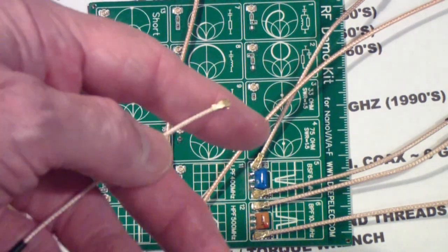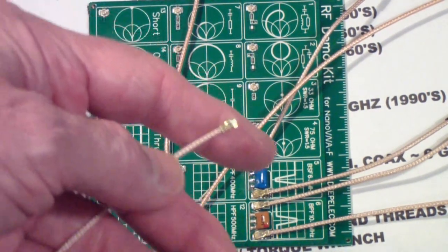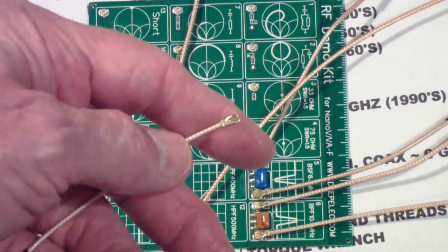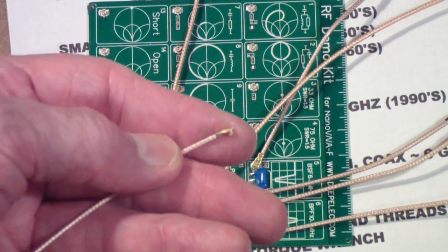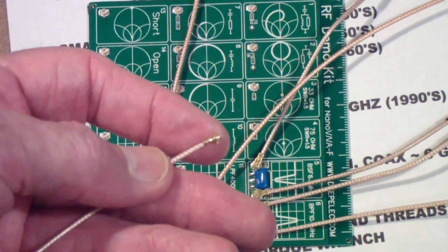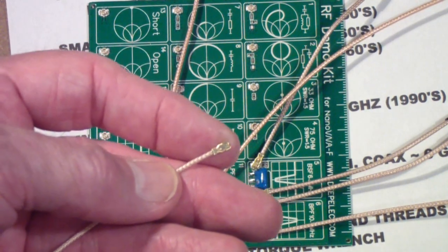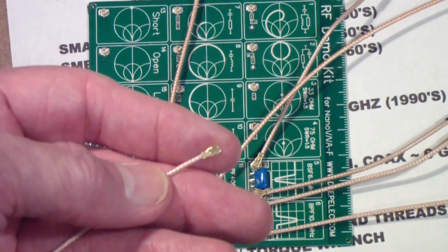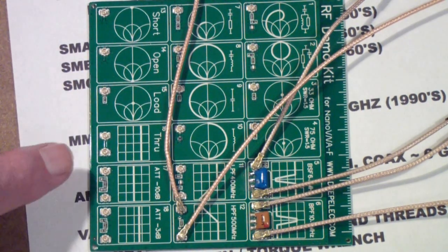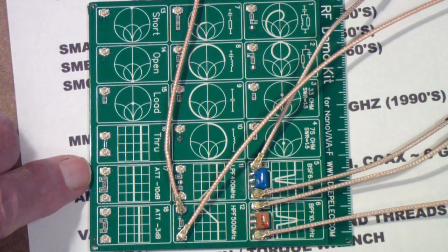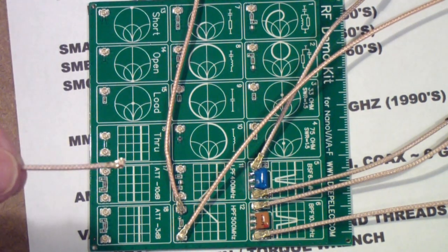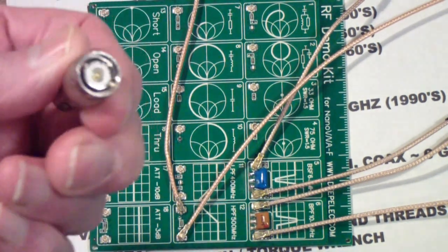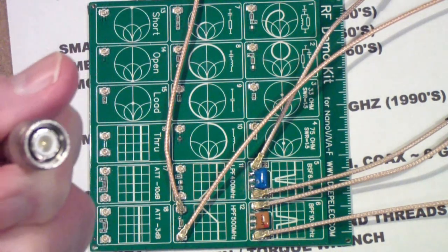So the UFL and later the AMMC by Amphenol are connectors intended to be very low profile, but they are coaxial connectors. I'm sure you can't see that, but there actually is a coax inside, a pin inside that connector, and it mates to sockets like this. Now, one thing that I will point out with these kinds of connectors, they are not intended to be mated and remated like something like a TNC or an N connector or a BNC.